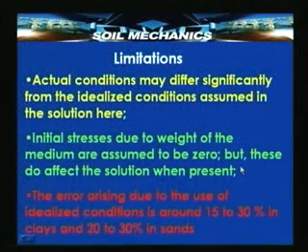The solutions obtained are deviant from the real stress values in the field. The initial stresses due to the weight are ignored because the medium is assumed to be weightless in Boussinesq theory. This also adds to the error in computation of the vertical stress, because the self weight of the material does impact on the vertical stress.